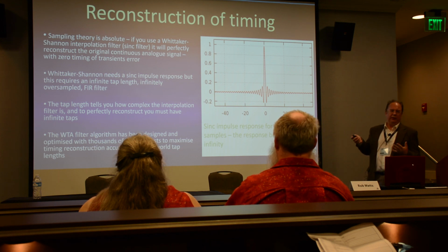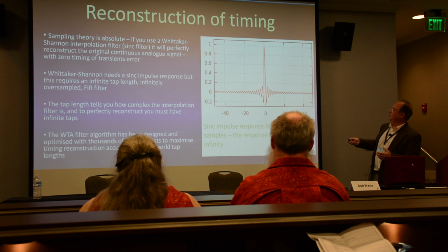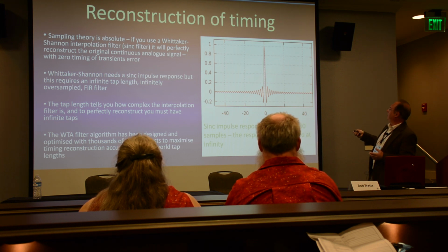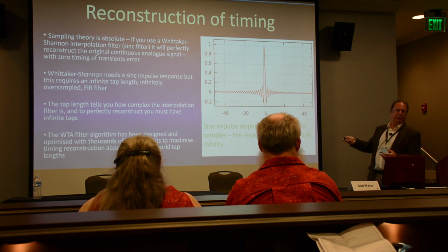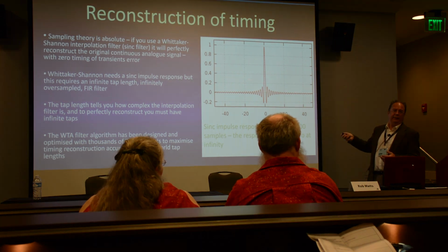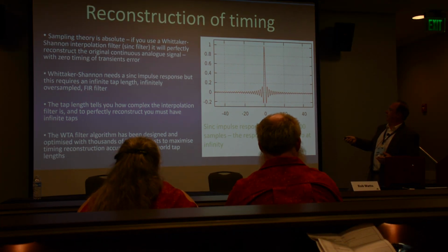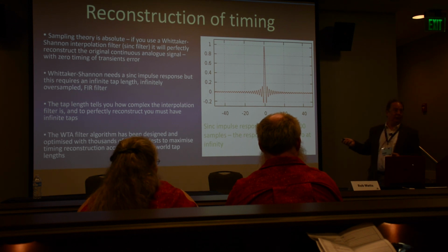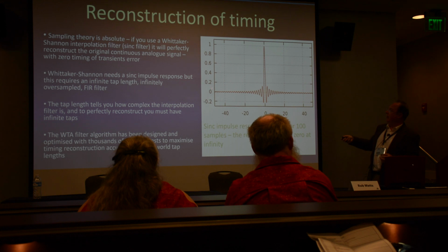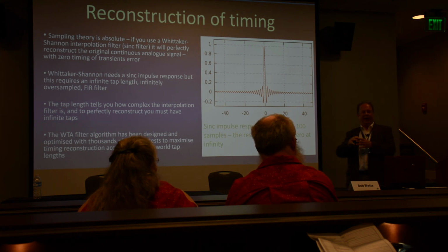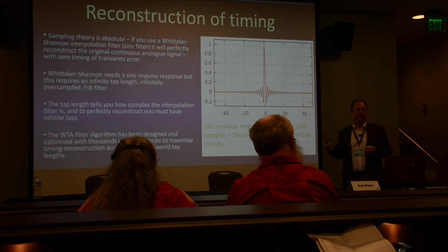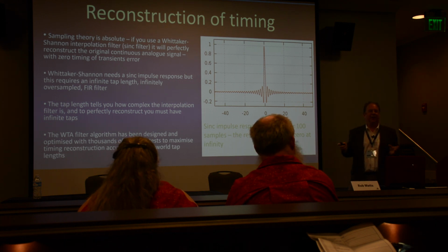Let's say you had a filter like this, a very simple tap length filter, and it was stopping at this point. This would actually be called a rectangular window function, because you take the perfect sinc function and you just chop it off. If you then use that as a filter, you get some very bad results. It's pretty awful as a filter.